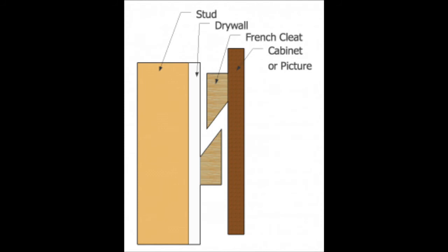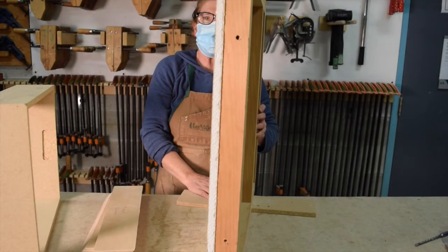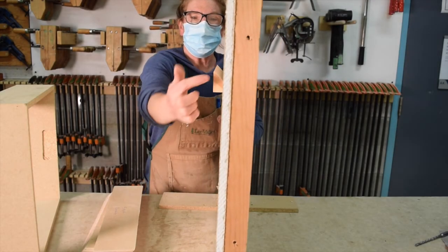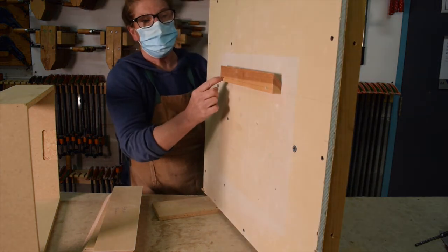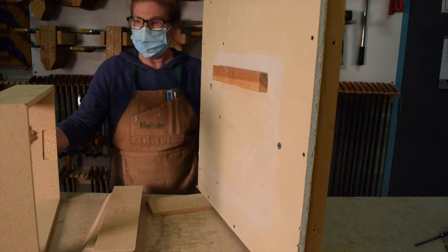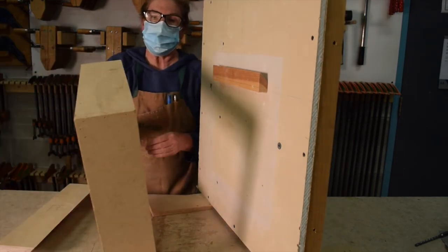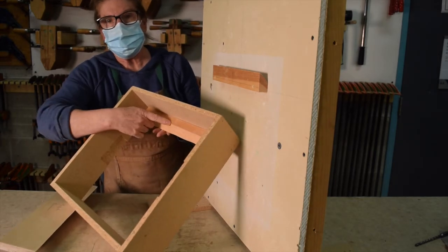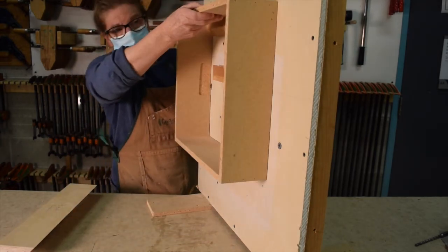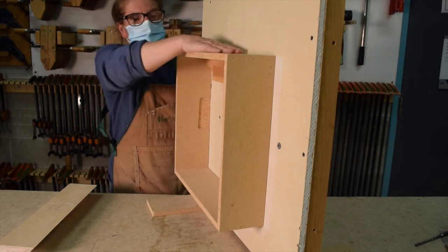And we know the fasteners that we can use depending on what kind of wall we're attaching into. So you can see here that I've attached half of this cleat on my sample wall. We know one of those screws went into an anchor and the other went into the stud. Here's the other half of that cleat on a 45-degree angle, and it just drops down.